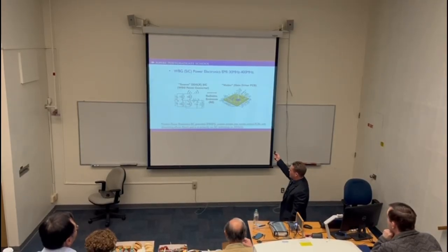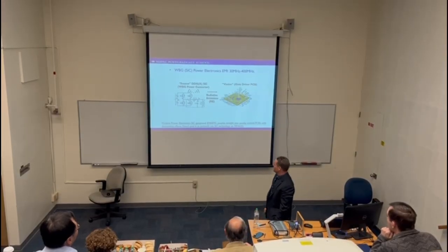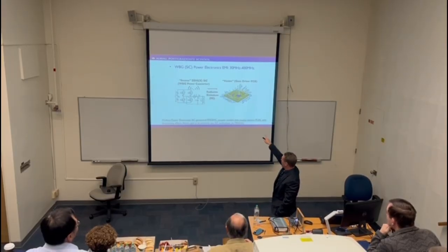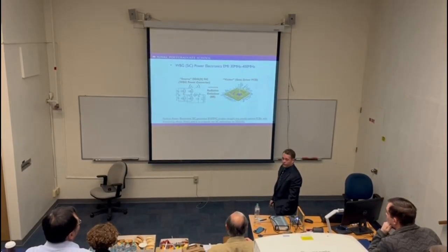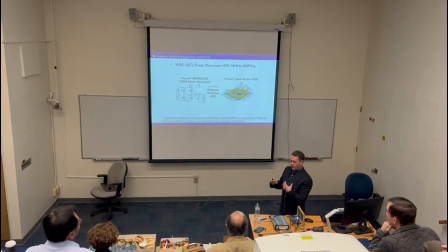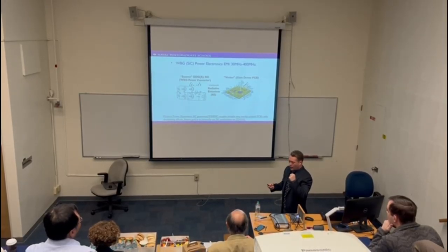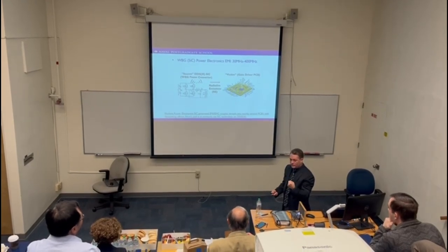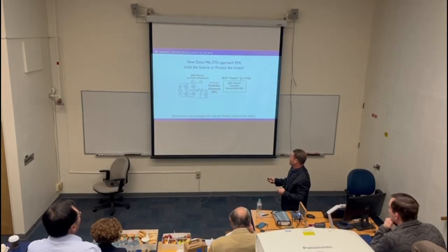And this is just a little example here, a little picture of a power electronics circuit from Professor Reed's class. You can see here some radiated emissions coming off and coupling to, for instance, a gate drive board, and creating lots of issues. So anything that's very adjacent to it, as you compact everything down, the circuitry doesn't have that much free space to attenuate some of the energy. So it's a direct coupling in the near field to a lot of these devices that are critical.